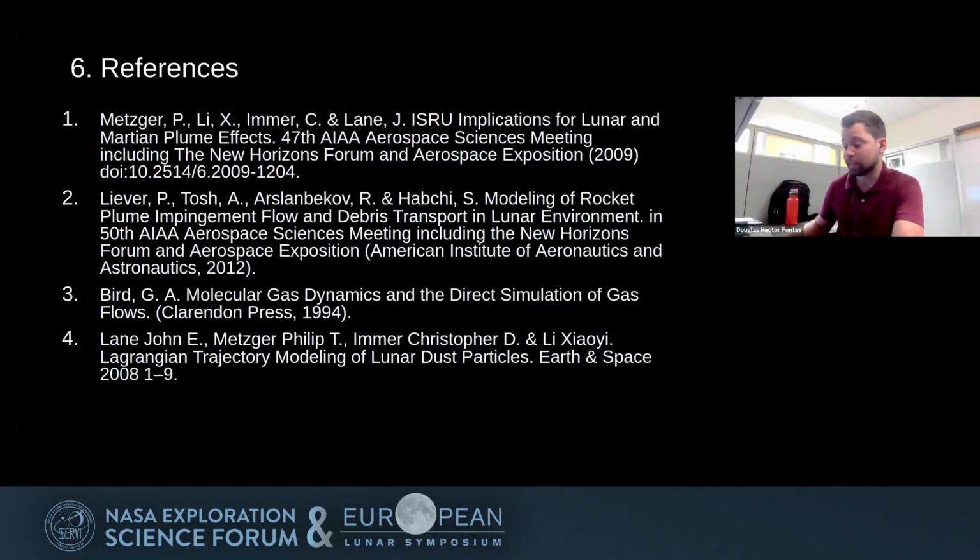Yeah, that's one thing that we need to explore. In fact, we assumed that the surface is flat in all conditions, but that's not true for the real case. So we want to model this using maybe a dynamic mesh with the DSMC code to be able to simultaneously have the gas flow producing some crater during the descent. But we are working on this yet.